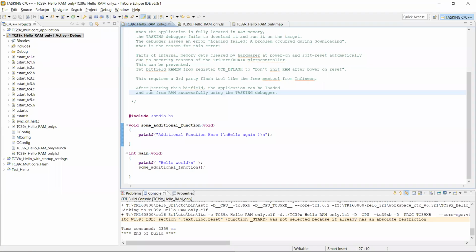As far as attributes go, for this particular setup, you don't really need attributes, but if you want to keep a function in the code and you want to avoid any kind of optimization, you actually want to keep it in there, even if it's not referenced or for whichever reason, you use the attribute used and protected.